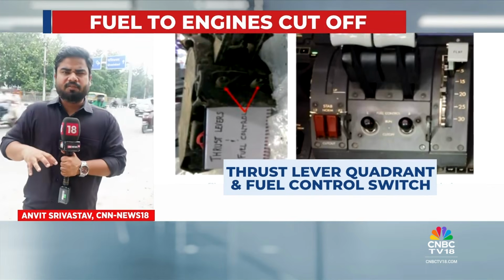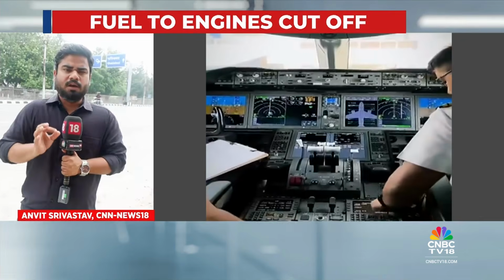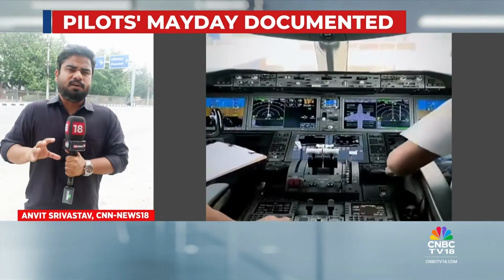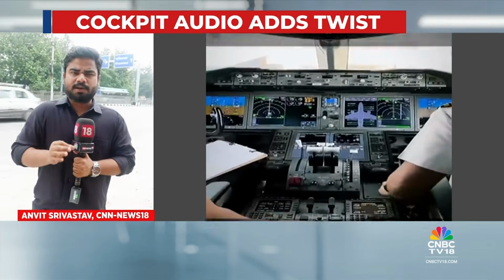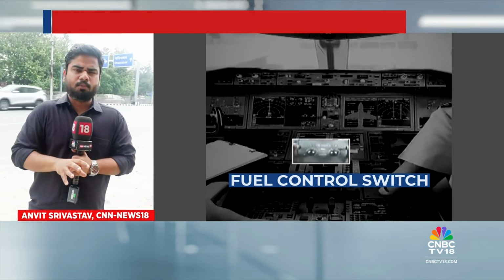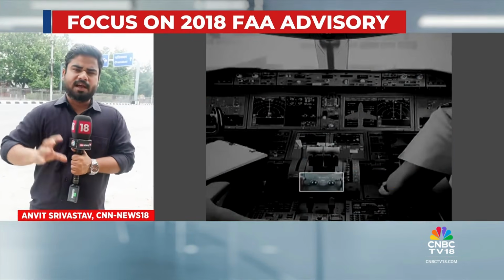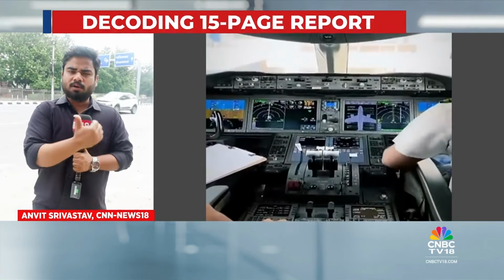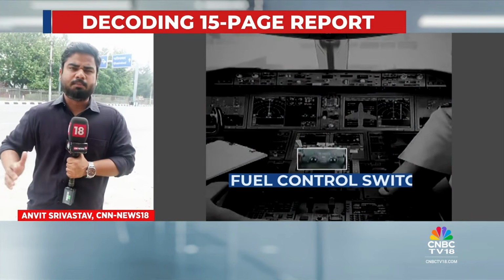Now, these are the preliminary findings which hint towards the main focus of the investigation being the engine fuel switches. But some details in this report have raised some questions, because we have previously seen that the RAT was also deployed, and the time has been mentioned at which the RAT, the ram air turbine, was deployed. But we also need to understand how much fuel was in the engines, allowing it to take off, and then the RAT deploys, and then the fuel supply is cut off, leading the plane to plunge and not allowing it to rise in altitude. So these are the details that we are looking forward to as the detailed report comes out.